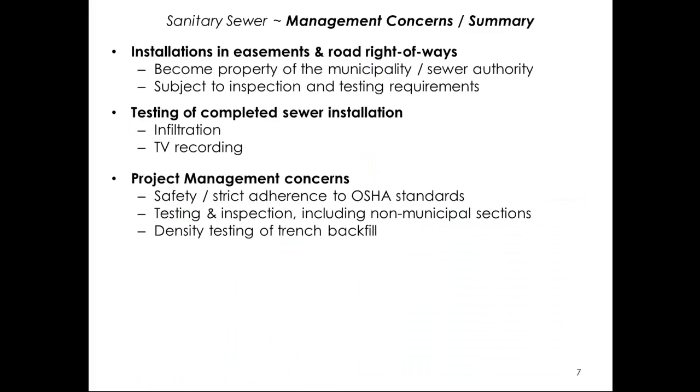Let's wrap this video up with a quick look at some of the management concerns you will need to consider for wastewater collection system construction. Generally, sewers are installed in public property and will be accepted and become part of a local municipal system. Part of the acceptance process will be testing of the lines for any infiltration, that is leakage, of groundwater into the system, and also the video recording of all lines to check for any trash or deflections that may impede the flow of wastewater.